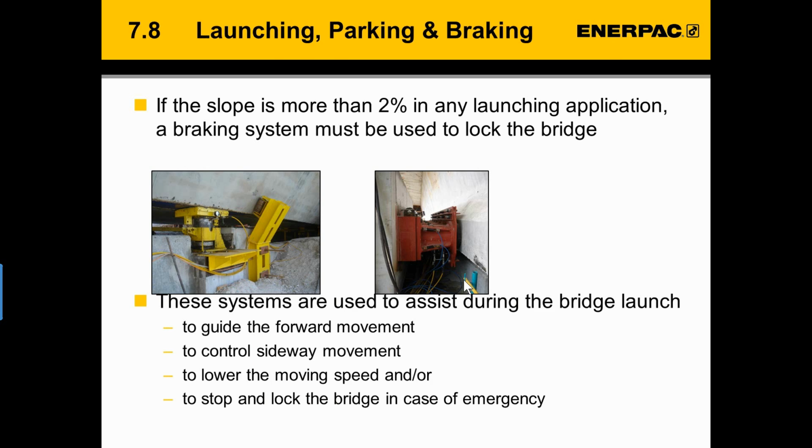A slope of more than 2 degrees will indicate that a braking system must be put into place for the launching operation. These braking systems are put into place to guide the forward movement, to control sideway movement, to lower the moving speed, and to stop and lock the bridge in case of an emergency.